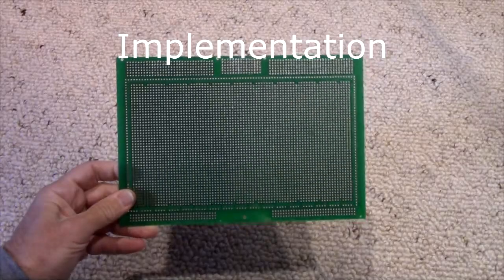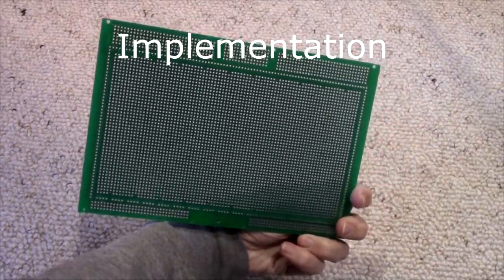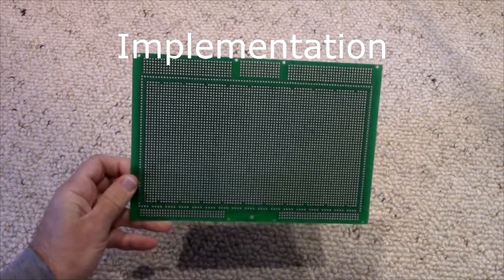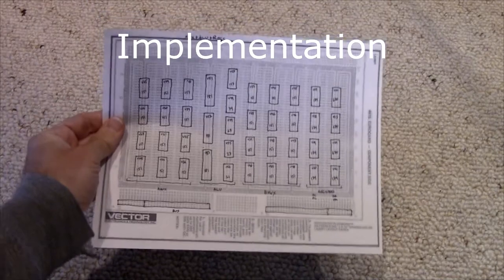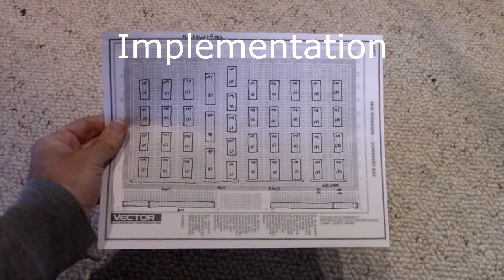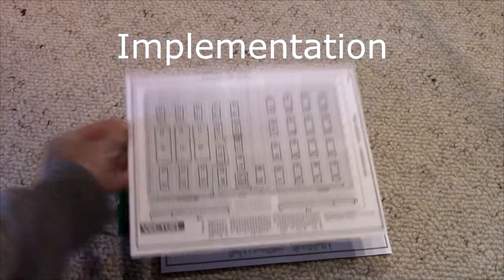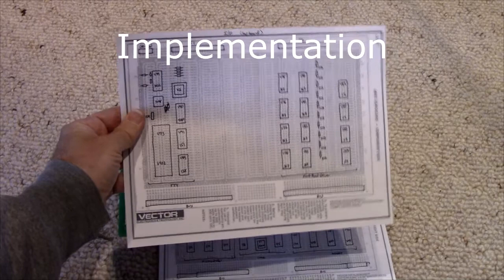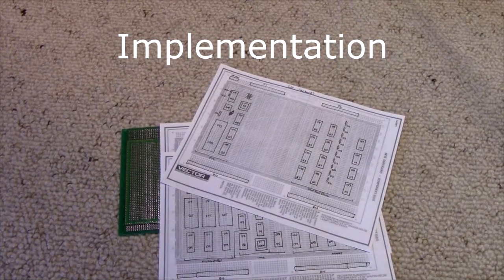So what I found is these Vector 4615 boards are called Euro cards, and I believe that I can fit it on 3 of these cards. One has the ALU and registers, another has the microcontroller, clock, and memory, and the third has the teletype interface and the front panel drive. Then there will be an actual printed circuit board for the front panel, which we'll get into later.